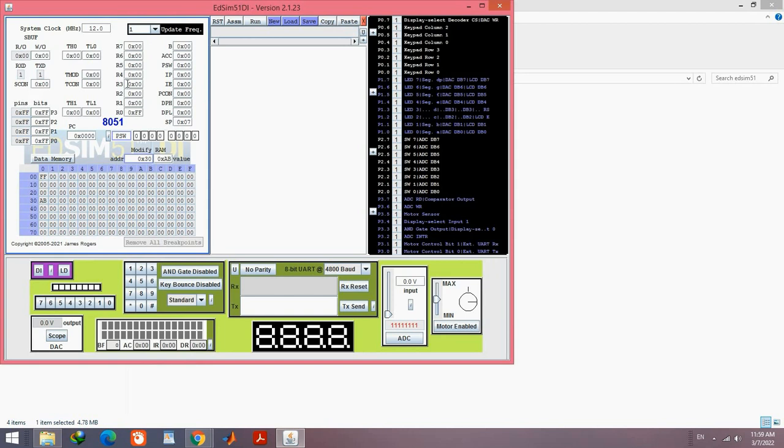By default, we are working with register bank 0. So when I mention, for example, here, initialize it to 0x12, the corresponding memory location is changed. So the R6 register is declared here. But also you can initialize any other locations by indicating the memory address here and its value in the value box. In this part, you can write your code.